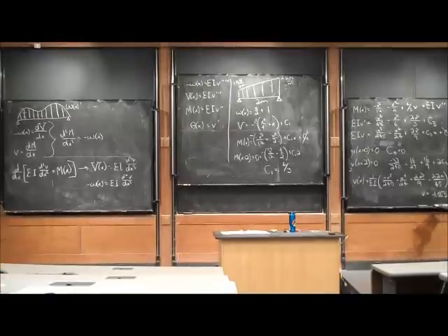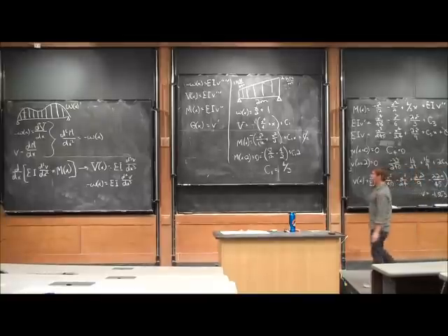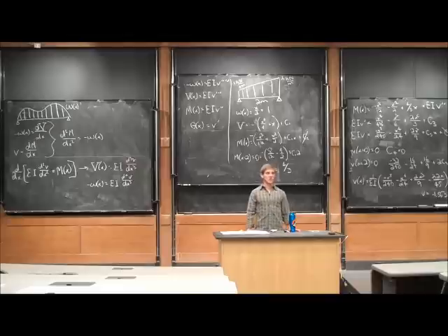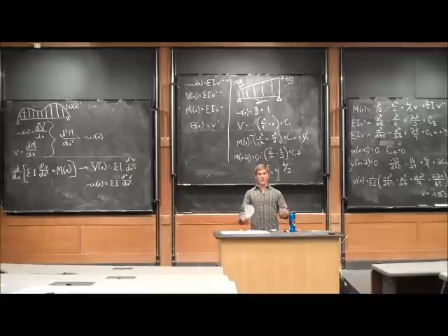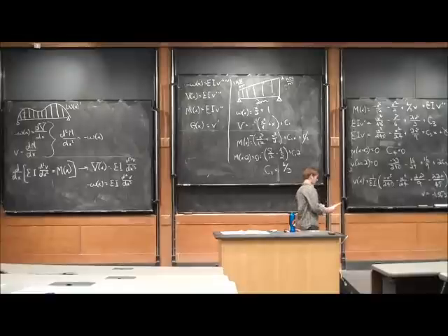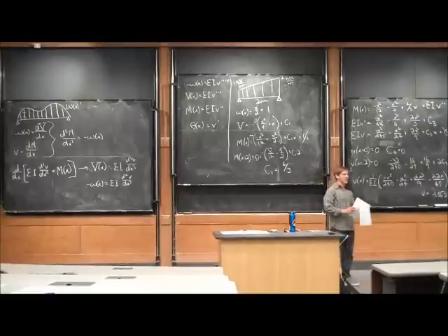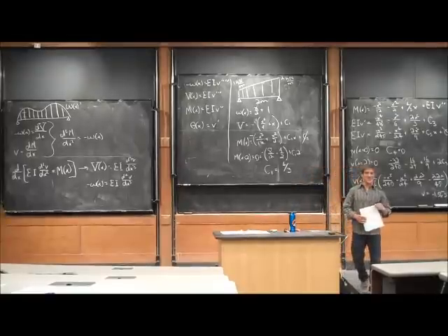Whenever we do these equations, we need to make sure we check that we have small deflections. These are not valid for large deflections. Once you leave the linear elastic portion of the material properties, these equations are not valid. These are only valid for very small deflections. How small is very small? Use your engineering expertise on that one.